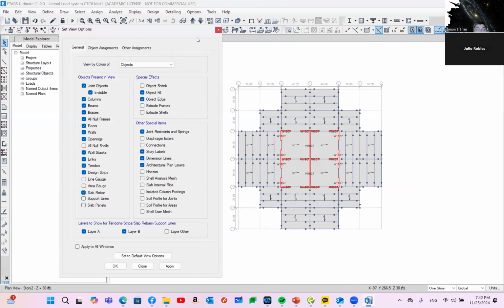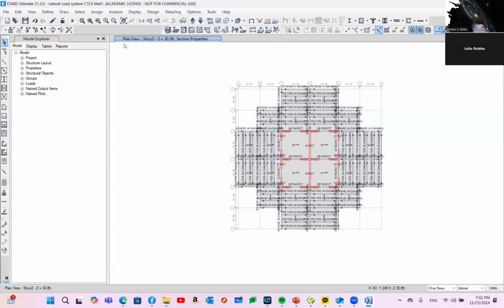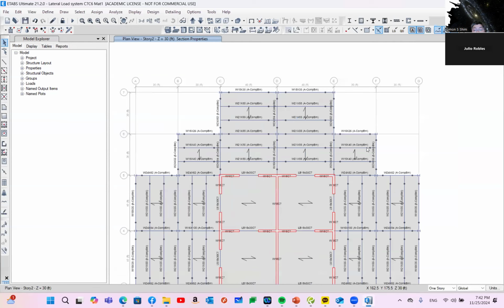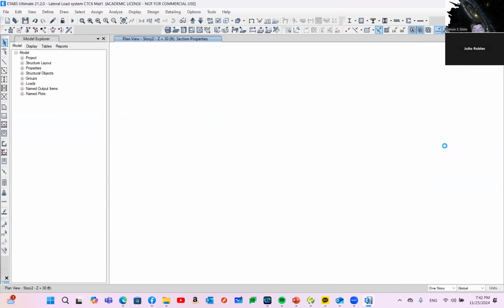What size do you have? The beam design? Okay, I'm looking at the 16, 21, 21, 16, 21, 18. All right, so you have various sizes because the spans are different, right? Yeah, so 40 and 30 feet, so 21 by 55. Okay, I'd say that makes sense.